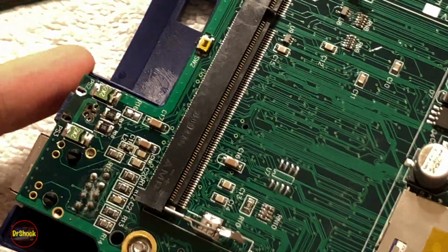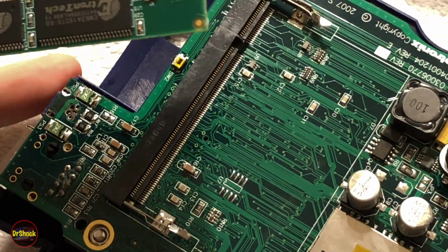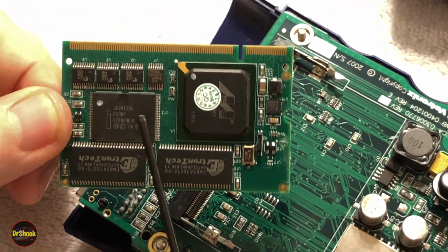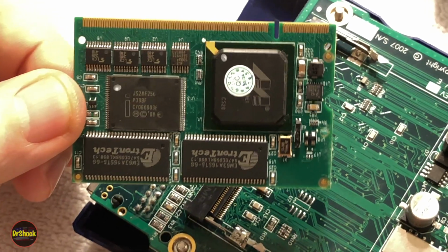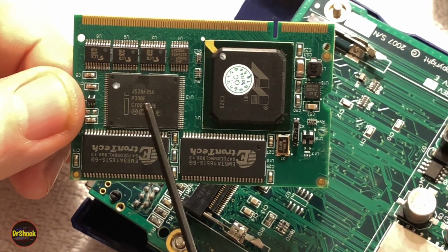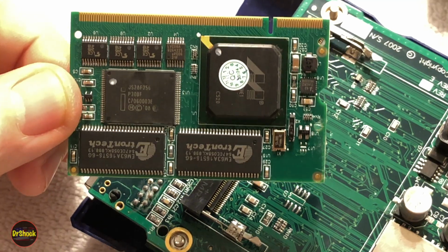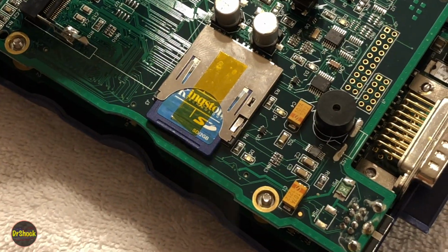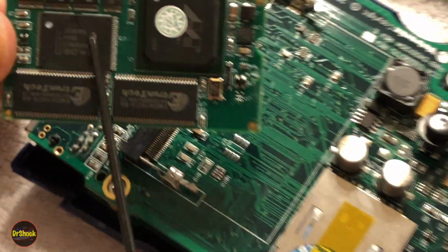This clone altogether, even if it was working, might be worth at most $75, right? So this chip alone would run you over 50. Next to that will be a flash, an Intel flash chip, 16 megabytes. This holds the core operating system when it boots up, and this is where the POST runs from. All that's over here on this SD card is the file system, and then all the utility programs that comprise the functionality of the device. All the real smarts of it are right here.